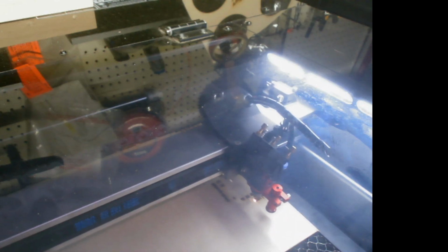Now for cutting, I should have my laser set to a higher pressure, around 21 to 22 psi for cutting. That makes nice clean cuts without leaving all the scorch marks on the cut lines.